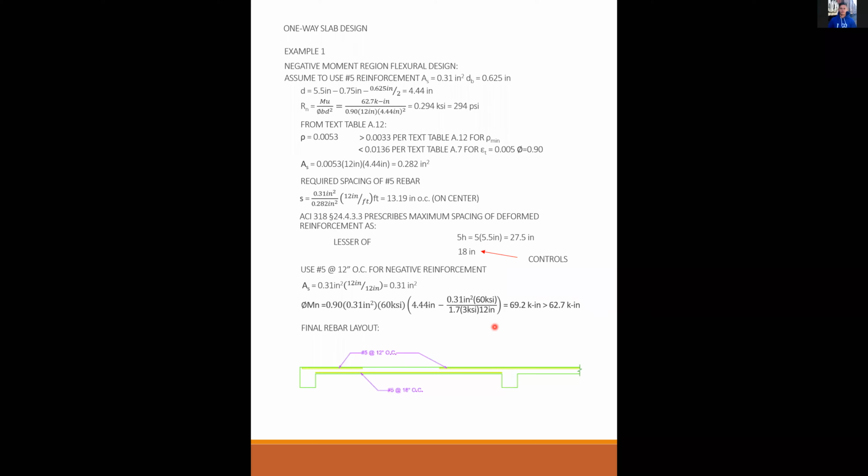Got it. Thank you. Okay. Contractors hate odd numbers, I would think so, until you get down to a really small spacing. If you're in the 3, 4, 5-inch range, then you put what you need. But if you're above like 6 inches, then I would say go to the nearest 2 inches.